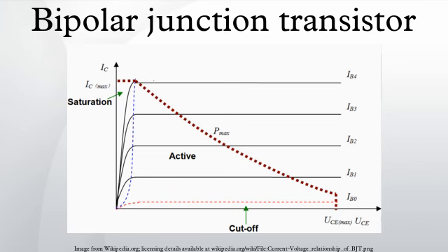The figure shows that this difference in bandgap allows the barrier for holes to inject backward from the base into the emitter, denoted in the figure as ΔΦp, to be made large, while the barrier for electrons to inject into the base, ΔΦn, is made low. This barrier arrangement helps reduce minority carrier injection from the base when the emitter-base junction is under forward bias, and thus reduces base current and increases emitter injection efficiency. The improved injection of carriers into the base allows the base to have a higher doping level, resulting in lower resistance to access the base electrode.